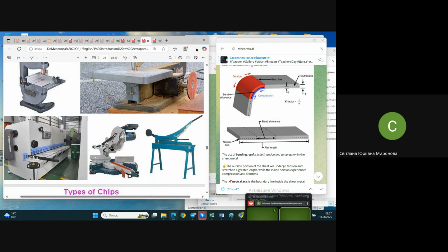Also somehow reminds the bending machine, but instead of a punch of complex shape and a cut die block, there will be two plates. These two plates are also sliding along each other with an appropriate clearance gap, and due to this, in a second, you may cut a very long sheet. For instance, you may cut strips with this guillotine shear.